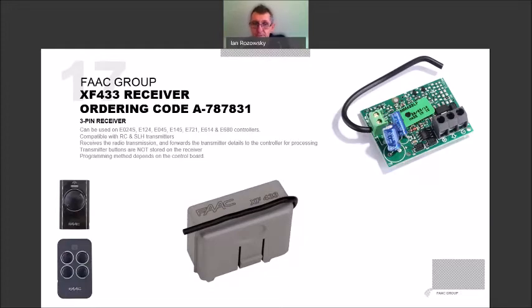You also can't expect to take this receiver off a control board, put it onto another control board, and have all the remote controls work, because as I say, the remote controls are not stored on the unit. So again, in a graphical format, we press a button on the remote, there's a transmission, the receiver receives that transmission, decodes it, and effectively just sends a serial number or a hopping code to the control board, and it's dealt with on the control board.